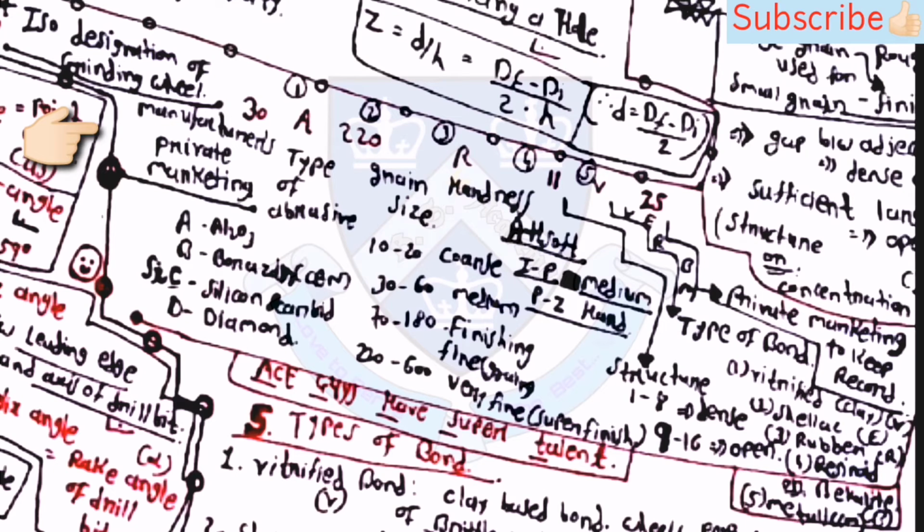The first one, 30, means manufacturer's private marketing, then A is the type of abrasive, then 220 is grain size, then R is hardness or softness, then 11 is structure and V is type of bond. Then the last one, 25, once again is the private marketing to keep the record.